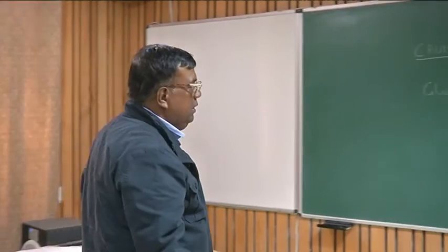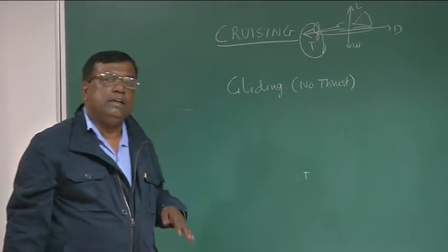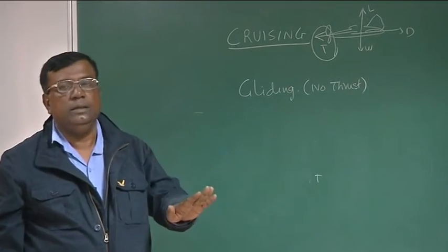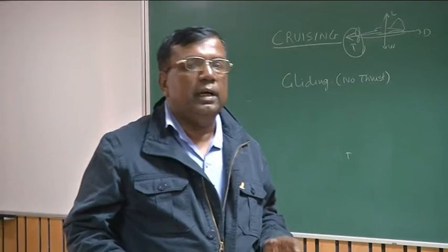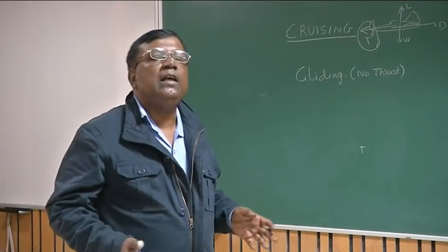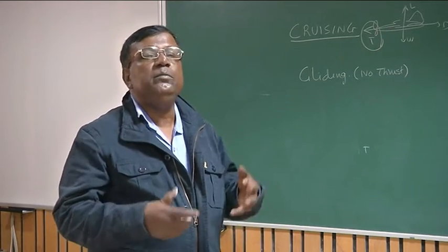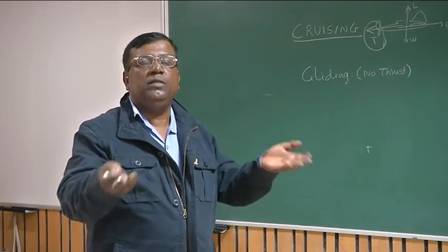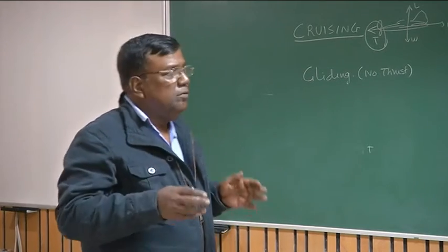Typically glider flight. However, you will realize there is another condition of flight when I am coming for landing. When I am coming for landing, the thrust is not fully on, right? Ideally, thrust should be as low as possible, or we say the propeller is windmilling, right? It's deriving energy from the atmosphere and rotating and developing some sort of thrust, very low.